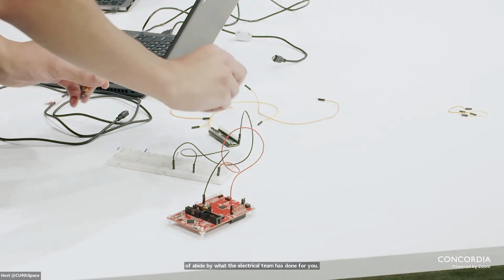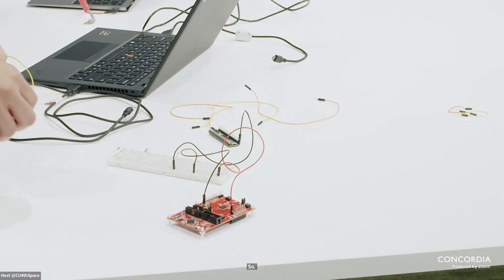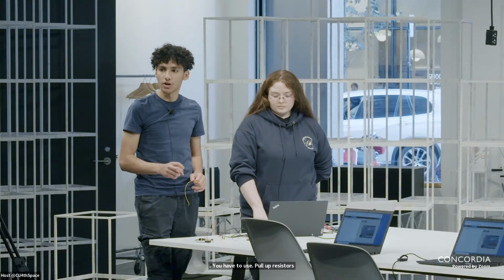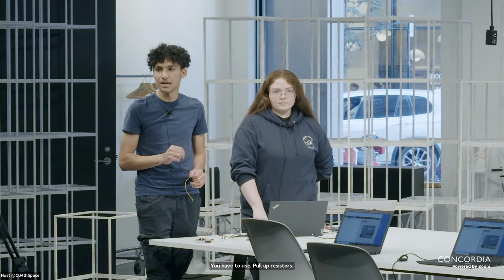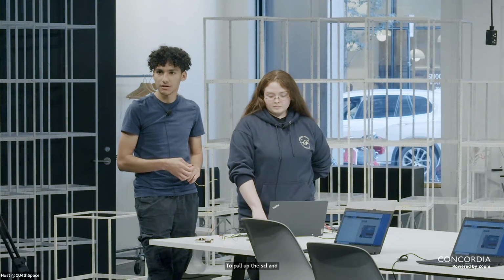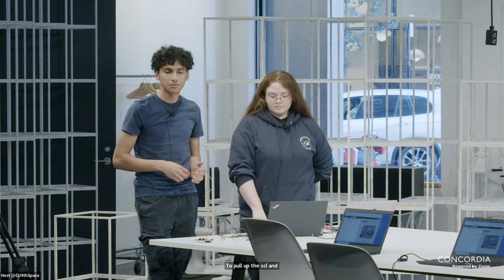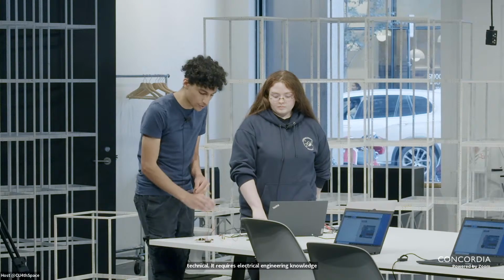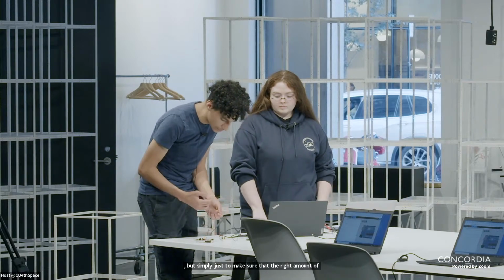So there's something called pulling up, and for I2C, you have to pull up. You have to use pull-up resistors to pull up the SCL and SDA lines. It's a little bit more technical. It requires electrical engineering prerequisite knowledge, but simply it's to make sure that the right amount of voltage is going through it. So I will just skip through that part, and I'll just do it here really quickly.